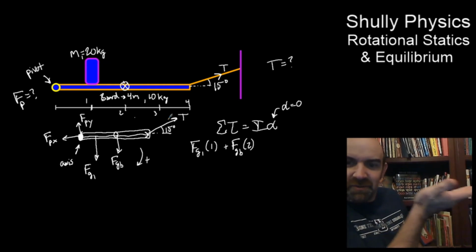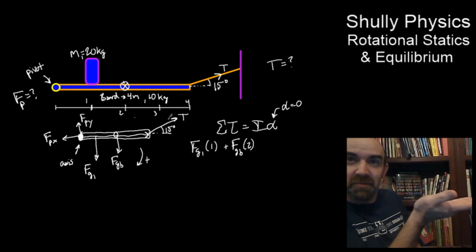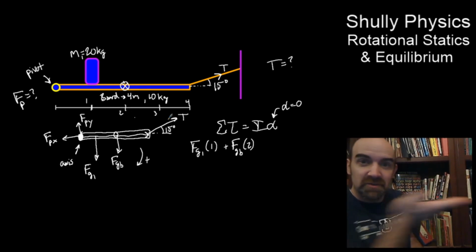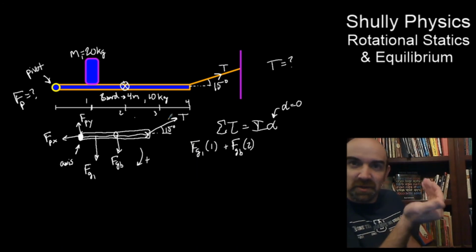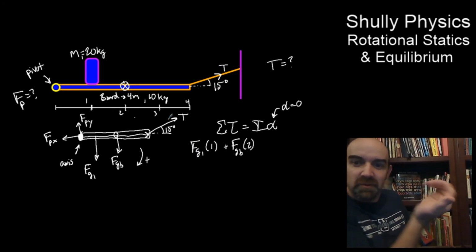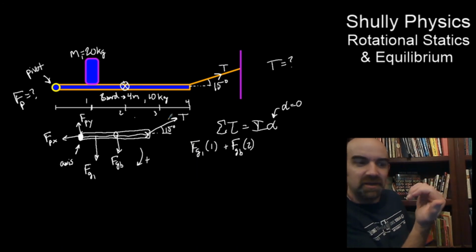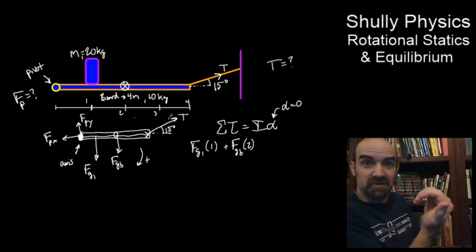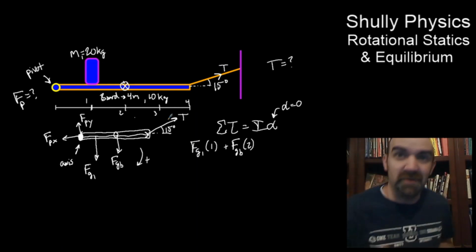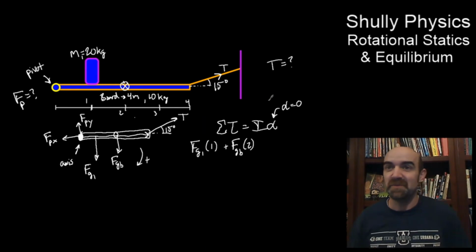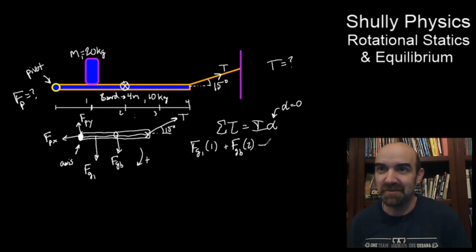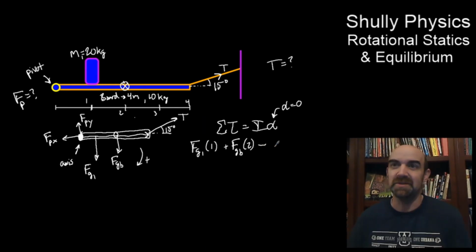R goes out this way in the direction of the R, the torque arm. We have to rotate our hand upward to slap that tension. So R cross T would give a right hand rotation this way. And if you look at that, what kind of rotation is that? That's a counterclockwise rotation. So we're going to have to indicate a negative sign here for a counterclockwise rotation.